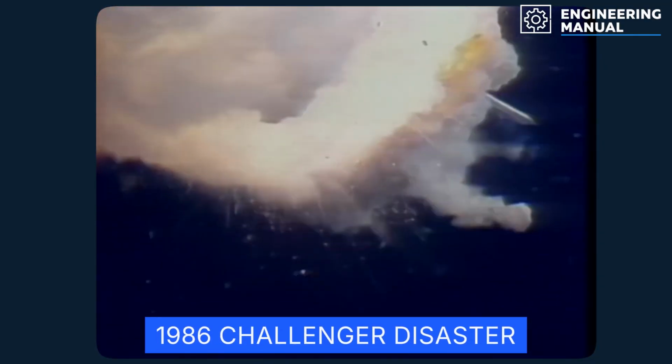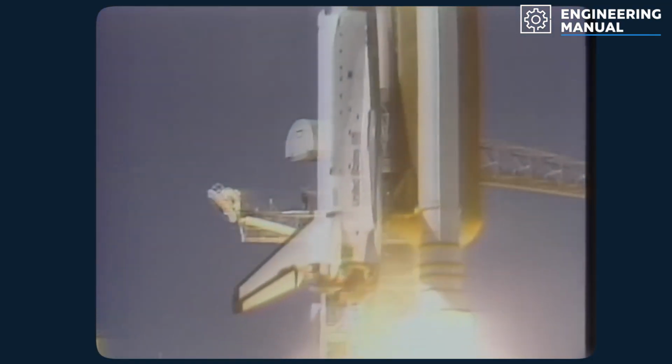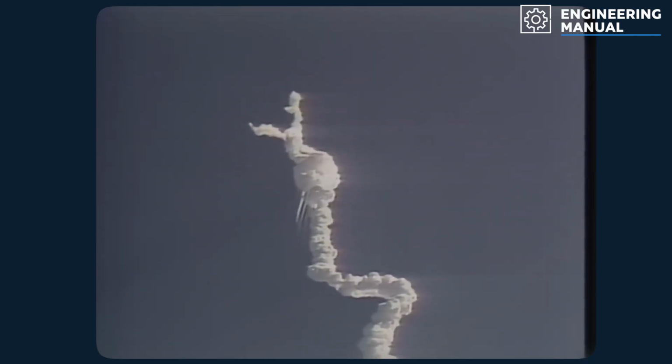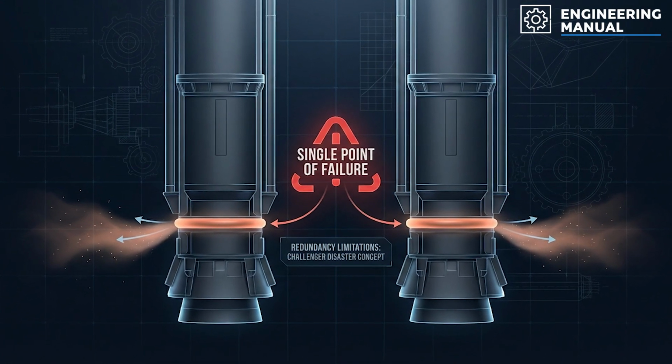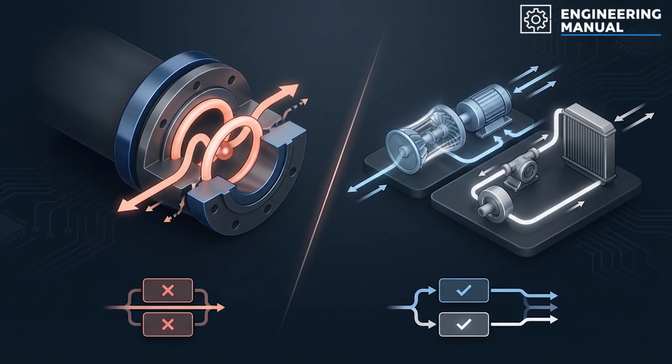That limitation became painfully clear in the 1986 Challenger disaster. The shuttle had redundant systems in many areas, but the O-ring vulnerability in the solid rocket boosters was shared across the design. Cold temperatures affected the sealing performance of both the primary and backup joints. In other words, the system had duplication, but not protection against the same failure mechanism affecting both at once. The lesson was crucial. Redundancy cannot rescue a design that has a single weakness built into all copies of the system. Duplication helps only when failure paths are genuinely separated.